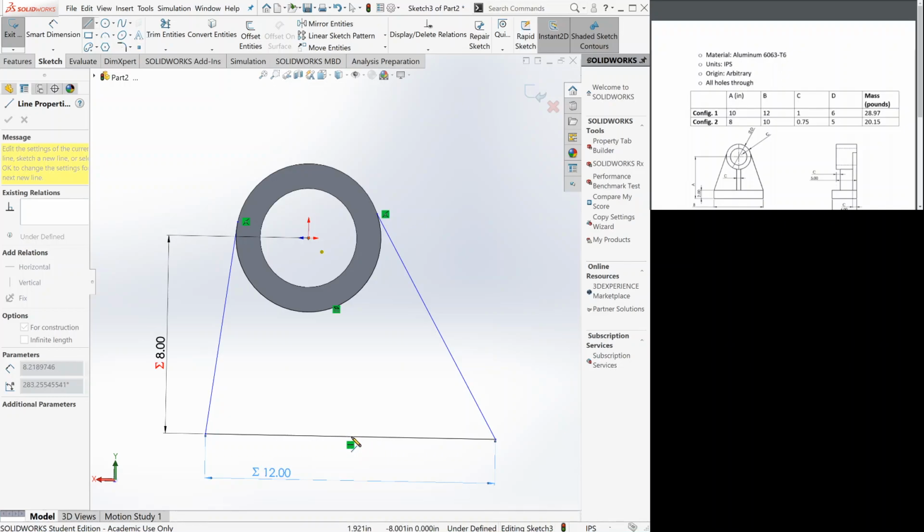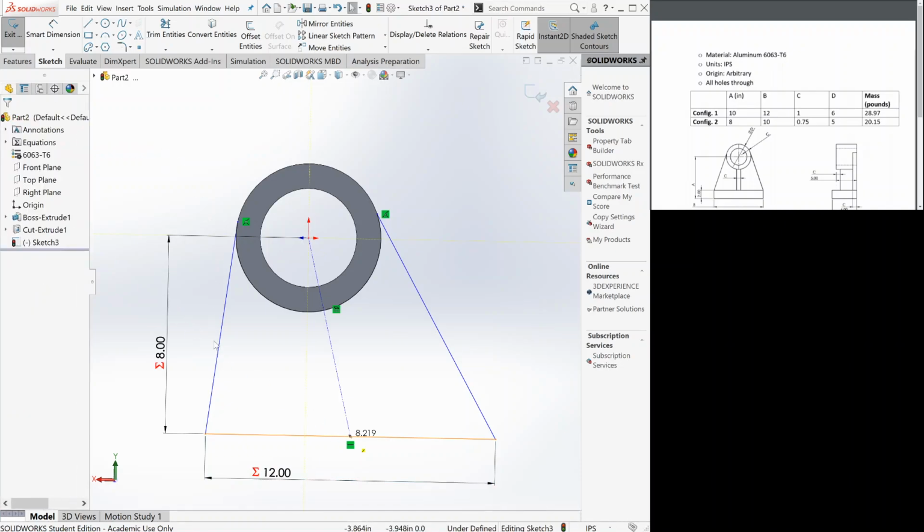So make sure it's coincident at the little part. If you see right next to my little tool, there's a little yellow highlight where it has a line and a green dot. That means it's coincident. So these 2 points are going to be connected perfectly. Okay, so click on that. Boom, now it's connected. Get out of the center line tool.